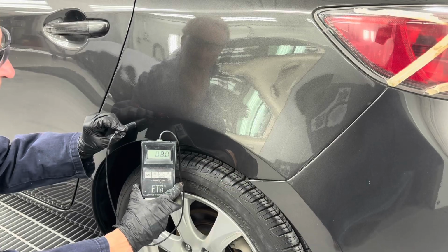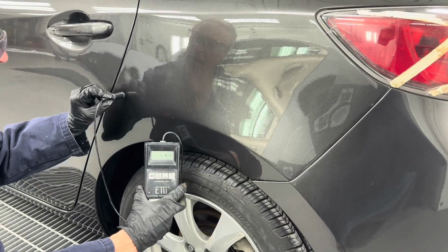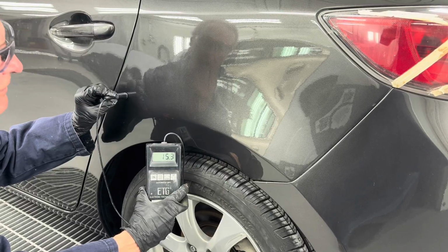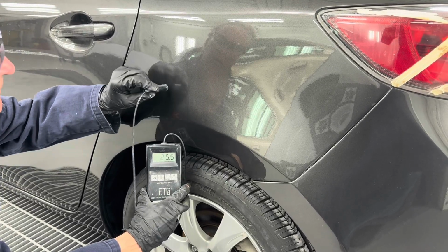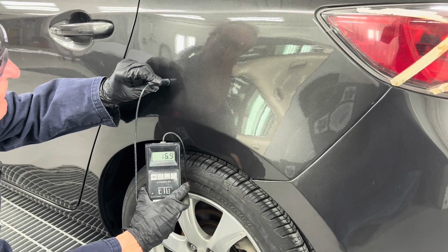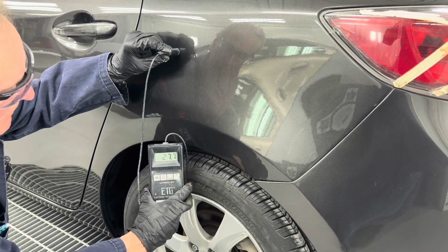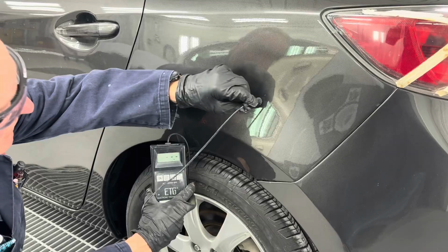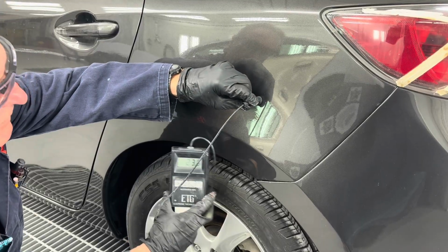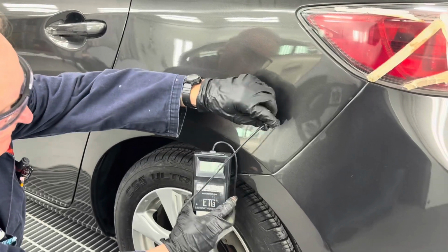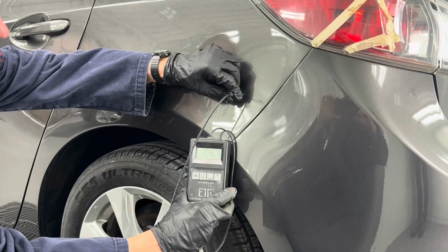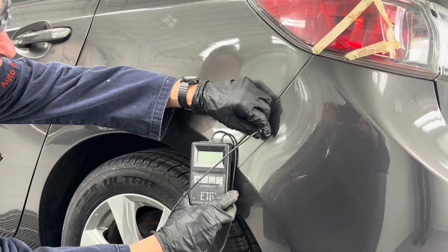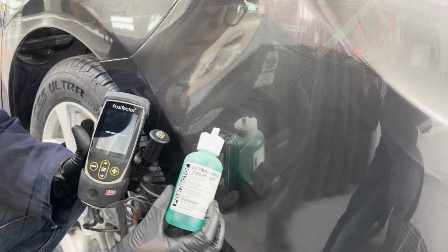A digital mil thickness gauge like this one can be used to measure the film thickness of dried paint by placing the end of the tool, the probe, directly on the dried paint. This uses magnetism to read the thickness of the material. You'll notice that the thickness varies across this panel because it has had repair in one area, which has body filler, and then there's other areas that have primer surfacer and multiple layers of paint. This tool will not read on anything other than ferrous metals such as steel.